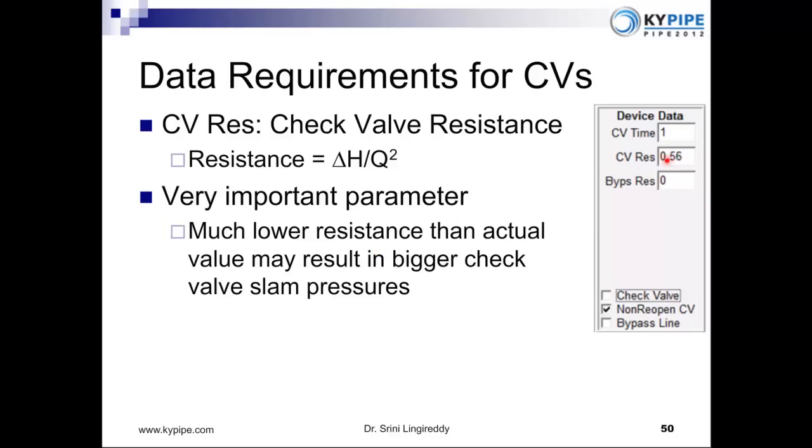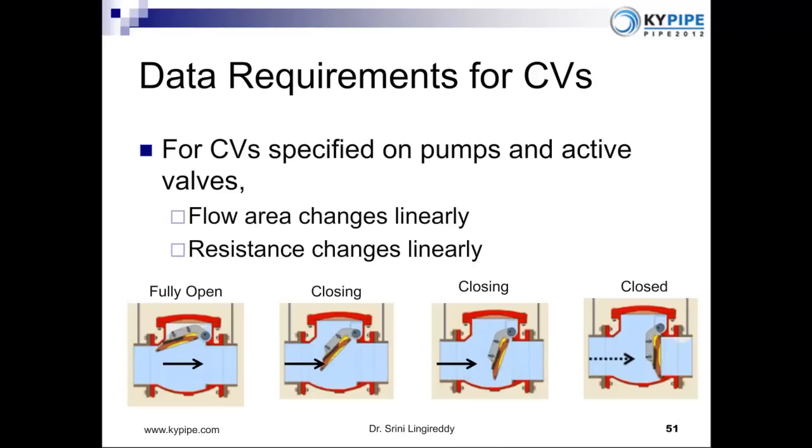At the same time, you don't want to use too much resistance, for the same reason. So you want to use the right resistance if you want to predict the right kind of pressure spikes that are expected in the pump station.